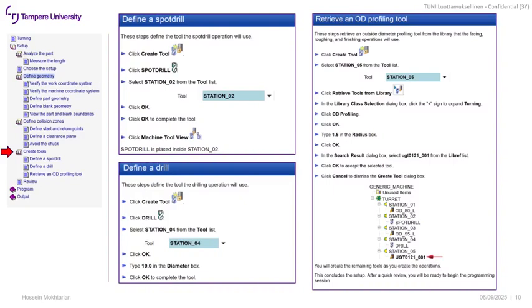Or if you are operating yourself, you need to make sure that, in this case, you allocate the outside diameter tool with a length of 80 to station 1, put the spot drill on station 2, and station 3 should have the outside diameter tool with a length of 55, and so on. Otherwise, there will be collisions and trouble with your drilling, even though your program might have worked perfectly fine in the software, but not in practice.